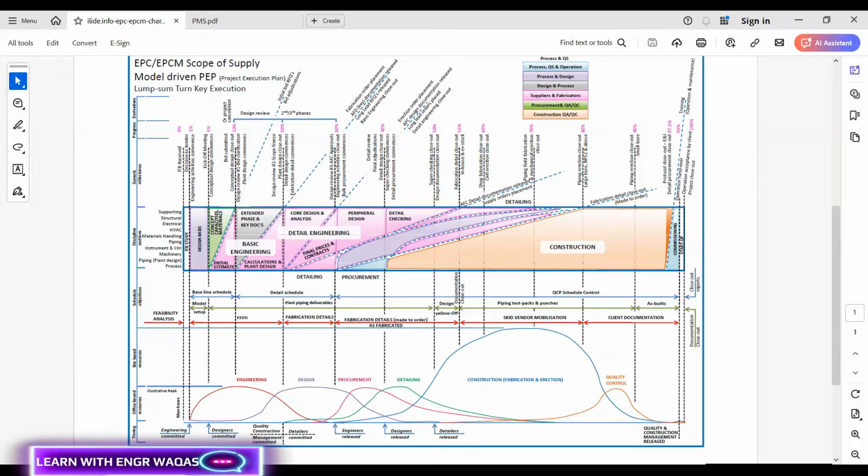Within this, you can have different contents like piping isometric drawings, hydro testing, and pneumatic test procedures. Whatever I explained earlier under plant piping deliverables, there is a repetition of the documentation, but here you can see more of the process, how to conduct it. Piping isometric drawings for reference, then static testing, how to conduct the procedure, a checklist for welds, flange connections, valves, material certificates, test results, and inspection reports.